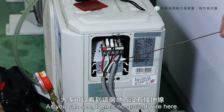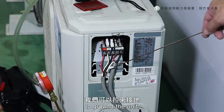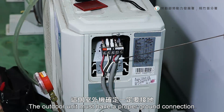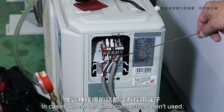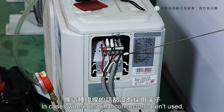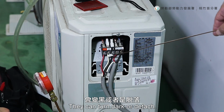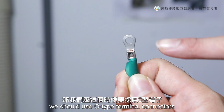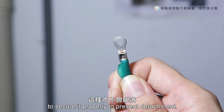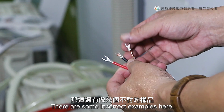That's very important. As you can see, there is no ground wire here. So we should add one from this wire to ground the unit. The outdoor unit must have proper ground connection to prevent electrical hazard during maintenance, in case where terminal connectors aren't used. Over time, disconnection may occur. They can turn dark or detach. If the ground wire is green, we should use O-type terminal connectors to secure it properly to prevent detachment and make sure it's secure. There are some incorrect examples here.